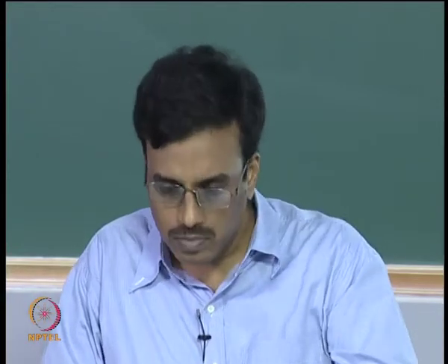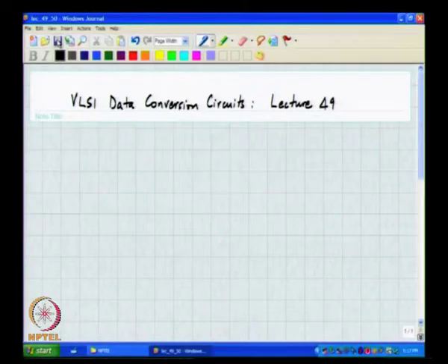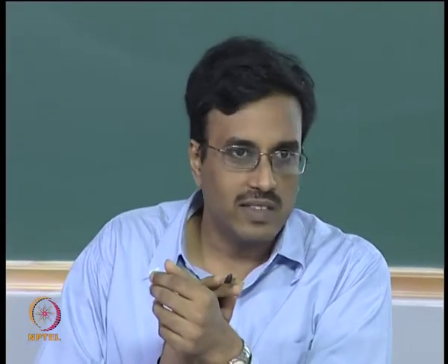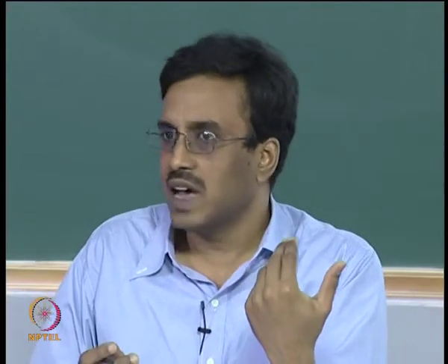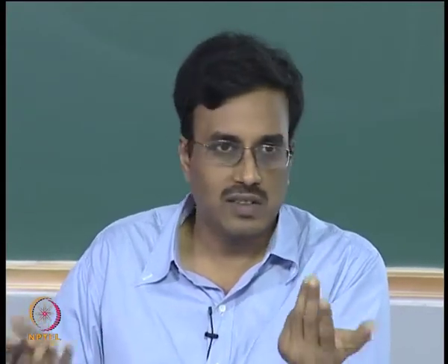All right. So, the last couple of points I wish to make with regard to the flash converter architecture is the following. And we got into this flash converter simply because we were discussing a delta sigma, and the quantizer in the delta sigma loop needed to be as fast as possible, and the fastest way of making a decision is the flash converter.